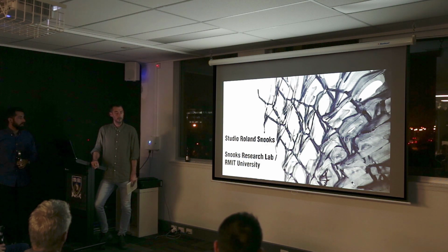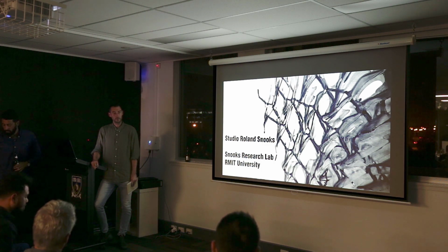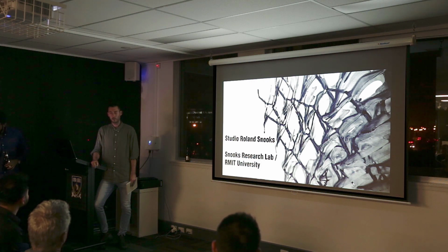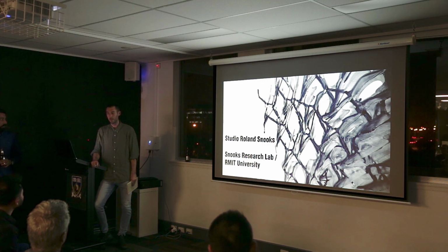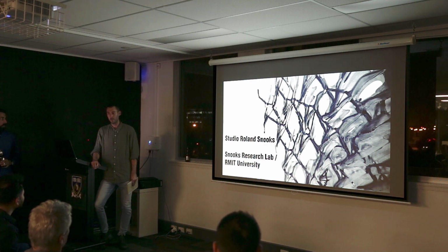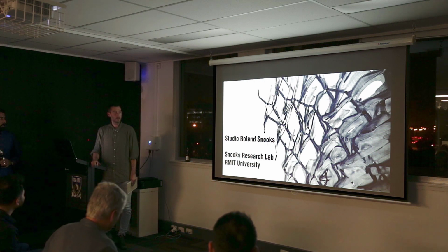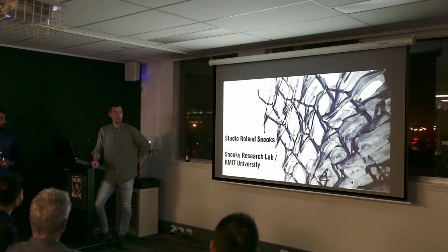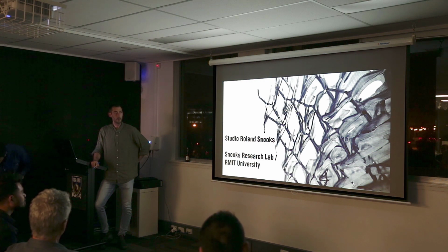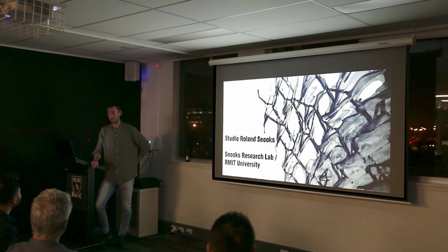Yeah, so the problem with most polymers is that they aren't great in compression, and specifically they're not great in point compression. So if any part of it is taking more pressure than another part, if it's not evenly distributed, you're going to get cracks and fracture lines that fall through it. They can take a fair amount of self-weight, but this thing is going to weigh probably about 500 kilograms. There's not really a plastic out there that can take that much self-load.